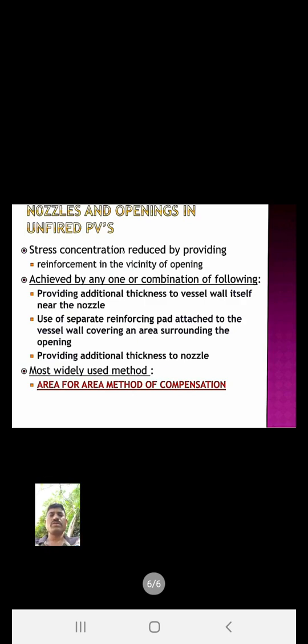Okay, stress concentration. How to reduce that stress concentration? Stress concentration is reduced by providing area reinforcement in the vicinity of the opening. Okay, how to achieve that? Any one or a combination of these methods we use.